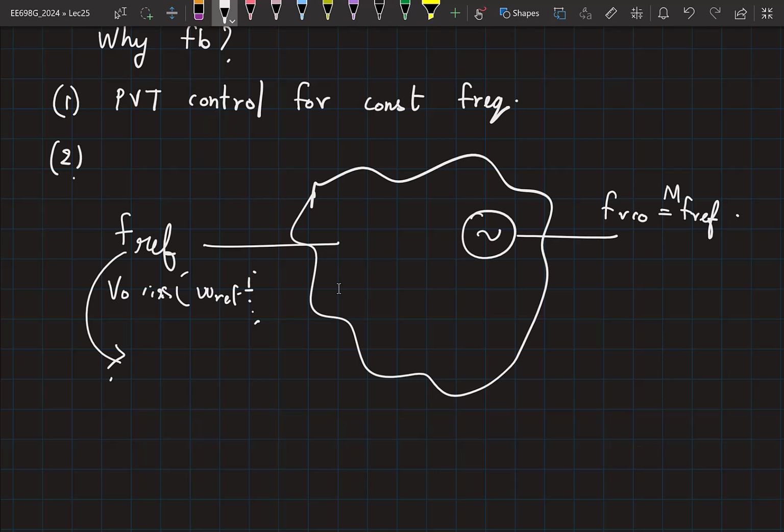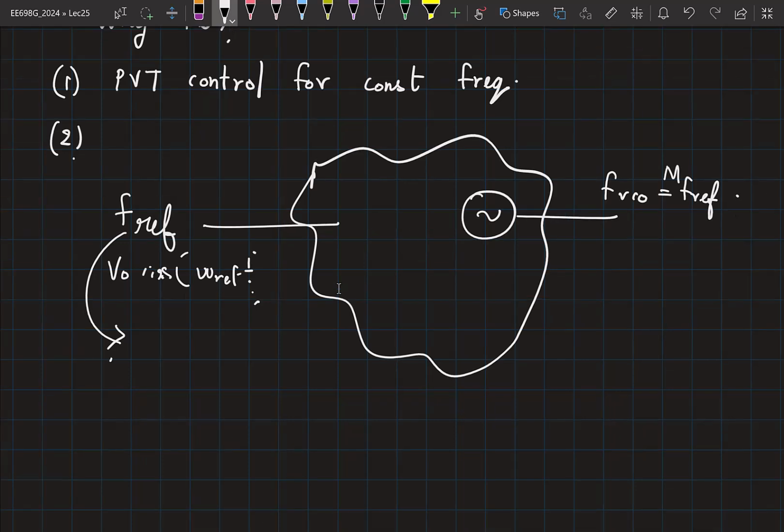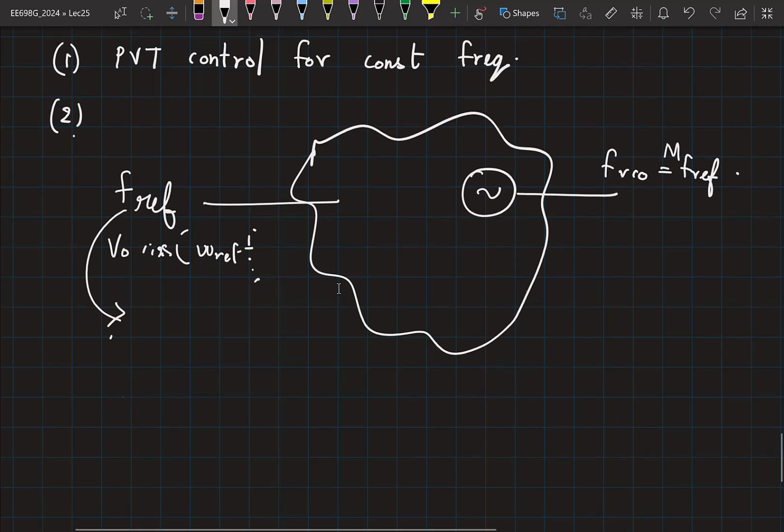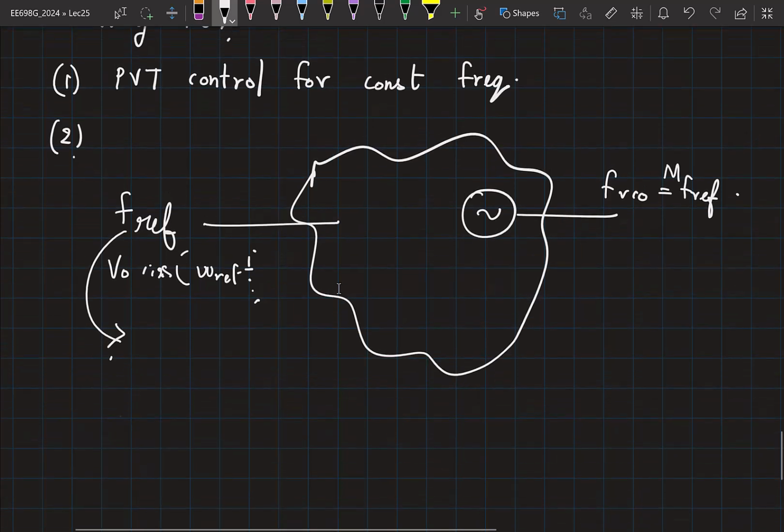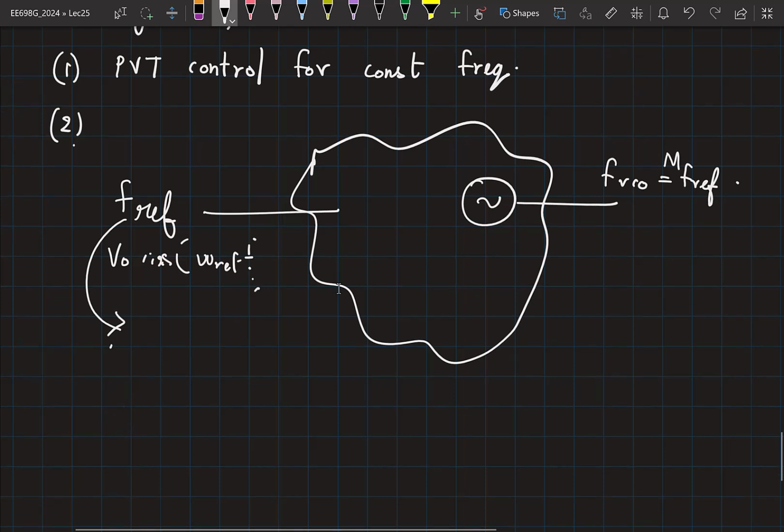And even if some of them are available for higher frequency ranges, they are more costly, right? But you wouldn't be able to pick out crystal oscillators at 5 gigahertz and then have tunability over it. So if you wanted multiple frequencies, you will have to use multiple quartz crystals. Can those crystals drive large loads? So you can bring that crystal signal on chip and then put as many buffers as you want. Right? Yeah. So these crystals are also bulky off-chip components.